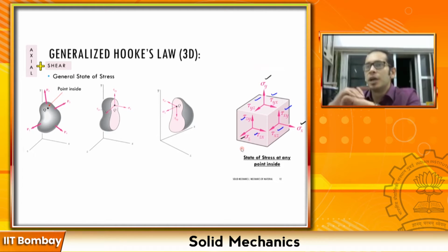Now remember one thing that we had derived, when we were looking at the concept of stresses and strains: the taus which occur on these mutually orthogonal faces are equal, right? That is essentially tau xy is equal to tau yx, tau yz equals tau zy, and so on.